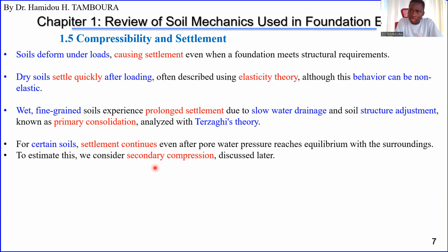So if there is water in your fine grained soil, once you apply load on that soil, the water will carry part of that load. And if the water starts being drained, the water will give the load slowly to the grains of soil.